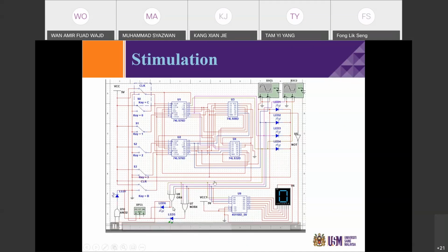After the owner leaves the spraying area, the Arduino Uno will send the low input to the counter and cause all the flip-flops to be reset. And this will happen in a very short while, maybe 0 point something seconds. So the counter will be reset, and then the system can continue to run again.